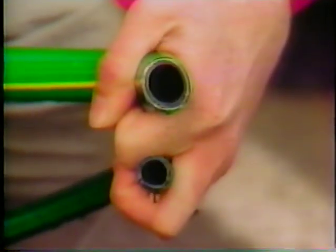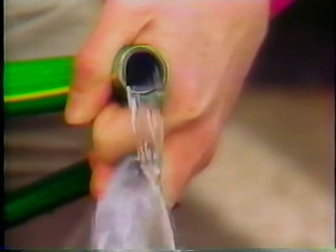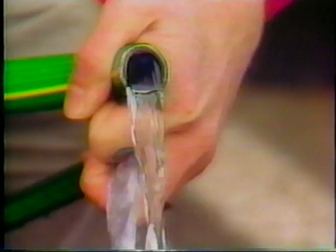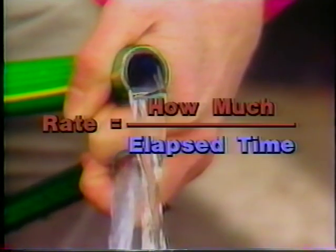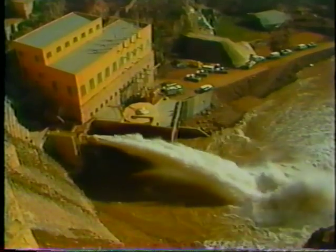Unlike mechanical systems, fluid rate is not concerned with how fast the fluid moves. The water is coming out of these two hoses at the same speed, but because one hose is bigger than the other, more water is coming out of the larger one over the same period of time. So, although their speeds are the same, the larger hose has a larger fluid rate. In fluid systems, the important factor is how much fluid moves over a period of time.